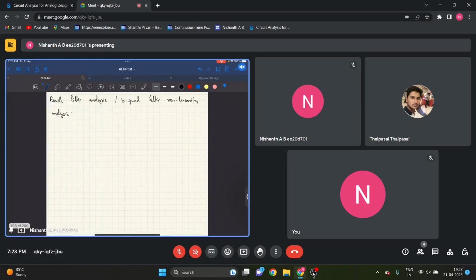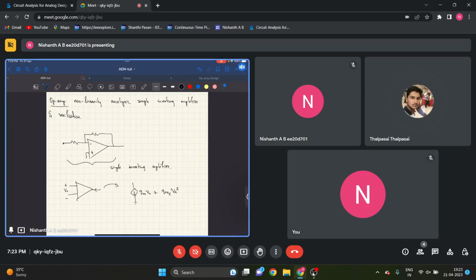That's what I was teaching actually. Look, in reality, all the MOSFET-based op amps are only non-linear elements, okay? If you model this op amp as a VCCS, you want to understand what is the Gm that you have to choose. By hand calculation, for a given Gm3, what is the Gm that you have to choose so that your non-linearity is less than a certain amount.